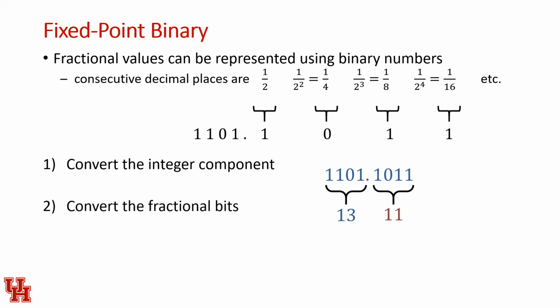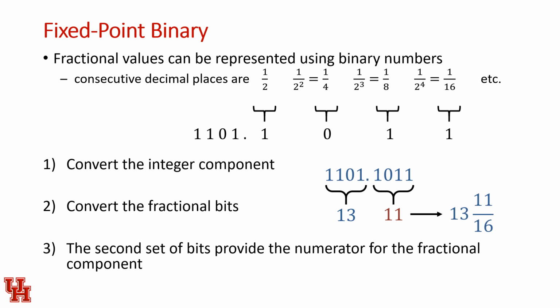We then convert the fractional bits to the right of the radix point to get 11. This value is the numerator for the fractional component. Since the 4-digit fractional component goes out to the 16th place, the final fractional part is 11/16.